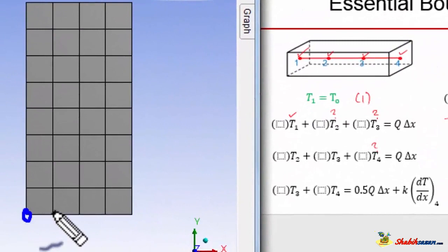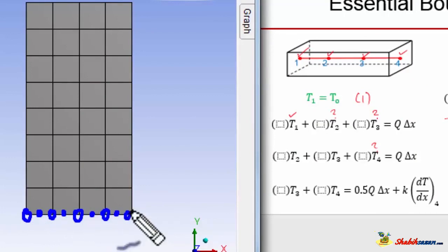So we have the corner nodes here, and then we also have the mid-side nodes. So it'll assign the temperature boundary condition for these 9 values. The temperature there will be set to 1 degree C. And you can see that the essential boundary condition will be satisfied exactly.